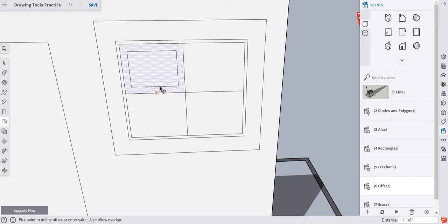And let's say I want that to be pulled in for 1 inch. So I go 1 inch and hit Enter. It will snap a 1 inch offset. Now what I can do is actually I can double click anywhere and it will repeat that same offset. So if I double click here, oops, wait, sorry. Undo that. I can go back to the offset.